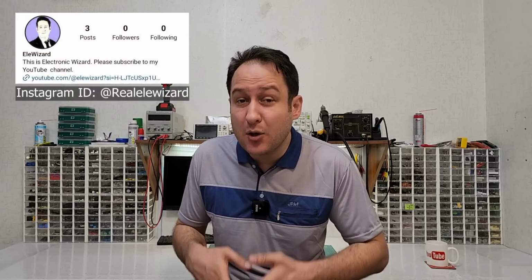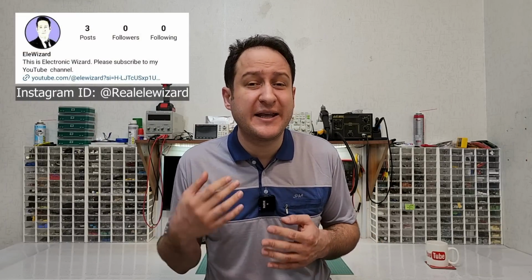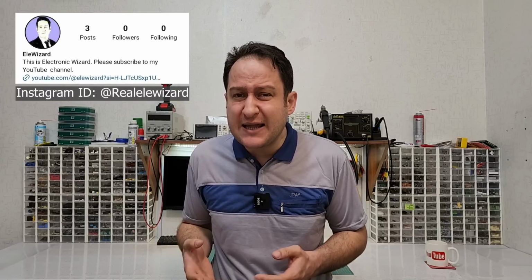Sometimes the load is a simple resistor and sometimes the load acts like a resistor. In such a case, the collector current will be calculable using Ohm's law. But if the load is not a simple resistor, you can refer to the data provided by the vendor, and if you don't have access to the vendor or to the datasheet, you can find the maximum current drawn by the load using an ammeter.